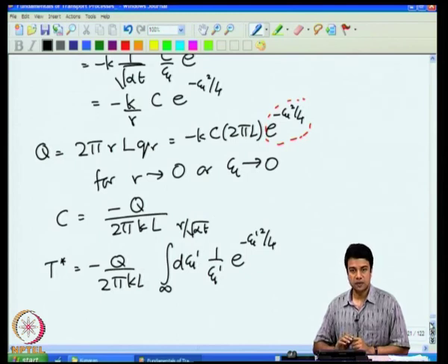If the heat coming out is fixed and the radius goes to 0, that means the surface area for heat transfer is going to 0. So, therefore, the heat flux has to go to infinity at the line source. The temperature also goes to infinity at the line source, but we can still get a solution for the temperature field everywhere else using this similarity solution.